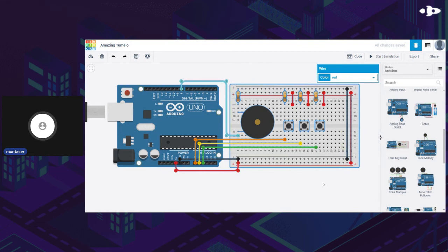All right. So the reason the breadboard is laid out like that is because a lot of components need power, and instead of running separate wires from one hole directly to everything, it's easier if you connect the power line to one of these rails, and now everything that's connected is going to get 5 volts. Similarly, to complete a circuit, if you guys have taken electronics, we need to have a ground. The way electric circuits work is, whenever a current flows in somewhere, the current has to flow back.